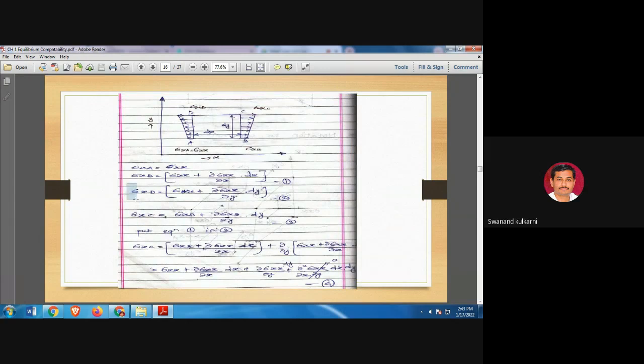So let us go for the next point now. Now see, we want the stress now at point D. Whatever logic we have developed to identify the stress at point B, the same logic we are now going to develop at point D. So sigma xd, what is the sigma xd here? Sigma xd at this point is nothing but the stress present at point A, which is sigma xx, but now this is vertical.